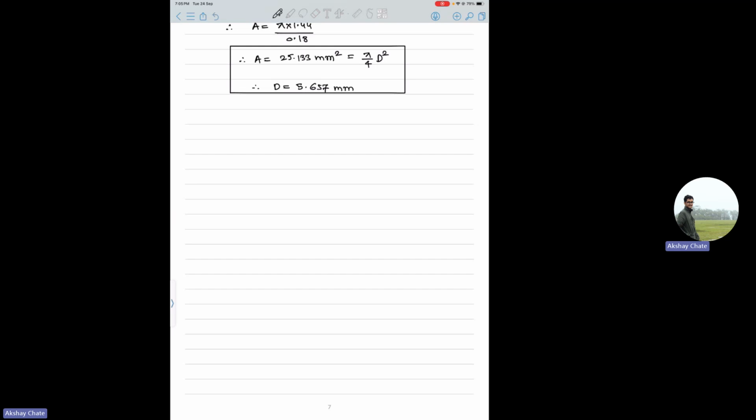So then there was discussion on this heat affected zone, etc. You should understand one thing here: this welding process is a permanent joint, that is fine, but it will always introduce anisotropy in your material at the weld zone.